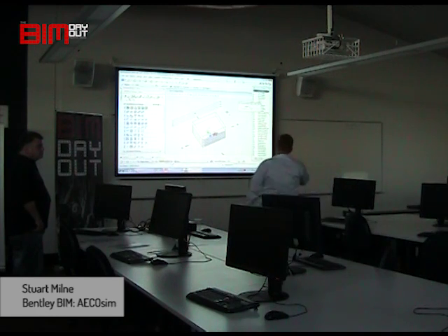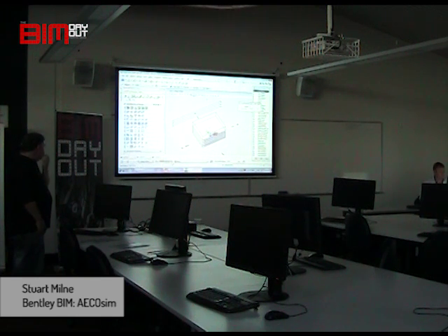Guys, what I just wanted to demonstrate quickly is this. What I'll do is very quickly, you don't have to do this, you can come a week or tomorrow and see me. Basically, these separate spaces need to be re-hooked up to the edge of the solid. It's pretty easy to do. I might just grab them like this, and then I'll deselect this one by holding the control key. And there's this tool here, update spaces. If I grab that and just click on the screen, it'll just re-hook them up.